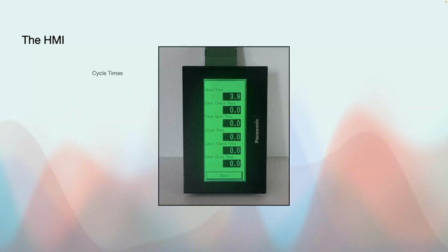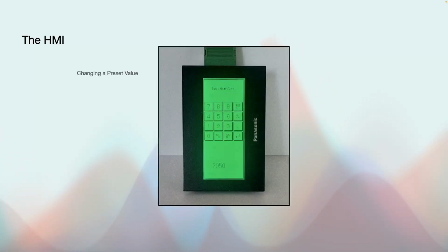If any of the door operator presets need to be adjusted for any reason, it's as simple as going to the preset you need to adjust. Tap on the number, and a numbered keyboard will display. Enter the new number, and set it by tapping the bent arrow at the bottom right. If you don't wish to change anything, just tap the escape key at the upper right.